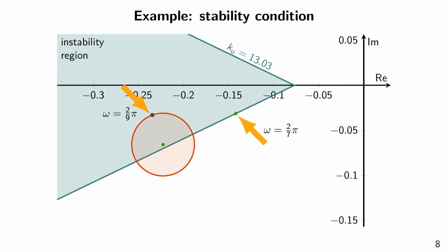For the nominal system, we get the upper bound Ku equals 13.03. Because of the addition of uncertainty, the slope bound shrinks to 6.96. This is considerably less than what we got for the nominal case, especially considering that only 15% uncertainty was introduced into the system. This demonstrates that even a small amount of uncertainty can cause a significant change in the behavior of nonlinear systems. Consequently, we see that vital insight may be gained by the inclusion of uncertainty in the analysis of nonlinear systems.